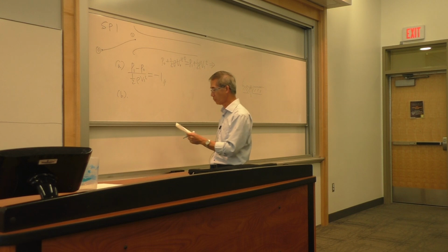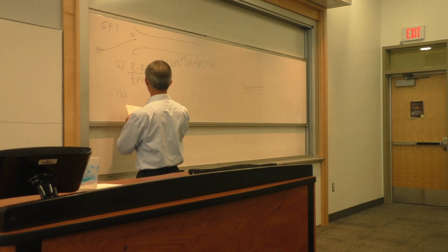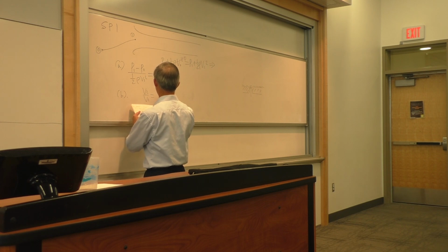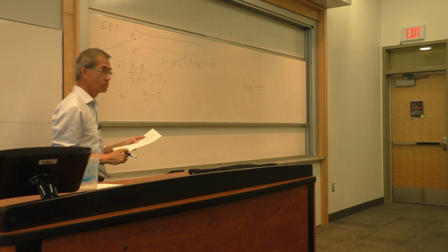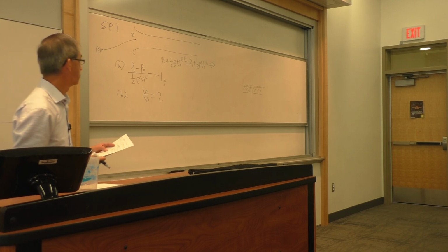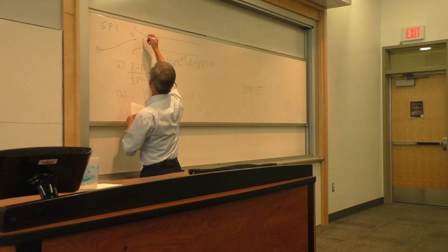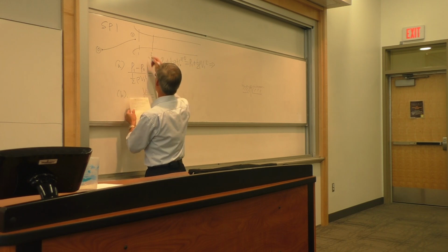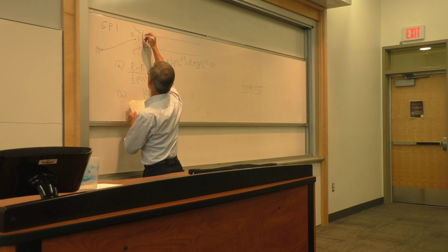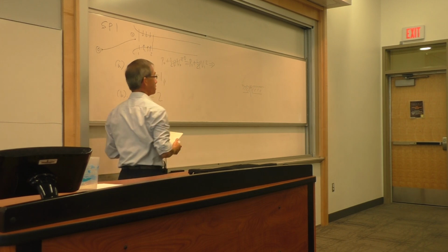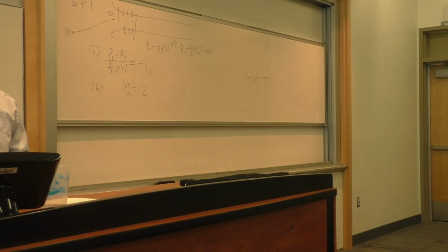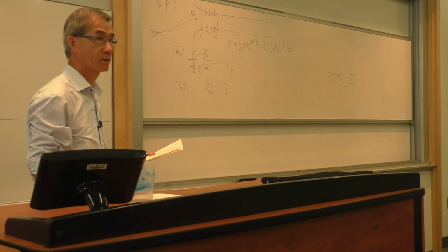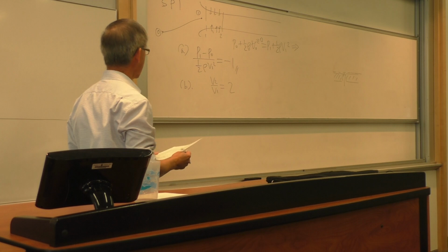So we know that Bernoulli is not to be used, and continuity based on the problem statement allows us to calculate the velocity at 2, with the same amount of injection into stations 1 and 2 as the fluid coming in on the left-hand side. So the velocity increased by a factor of 2 exiting station 2.